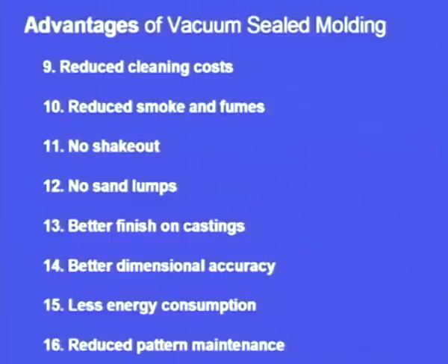Next one, reduced cleaning cost. In the case of the conventional sand casting process, after solidification, we have to break the mold. When we break the mold and take the casting outside, the casting will not be clean. Sand will be sticking to the casting. That sand we have to clean. Clay will be sticking to the casting. That clay we have to clean. But here, what is happening? The casting will be clean.